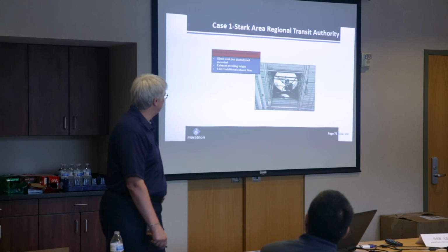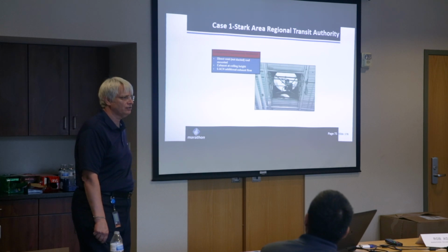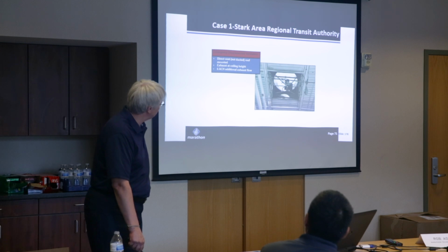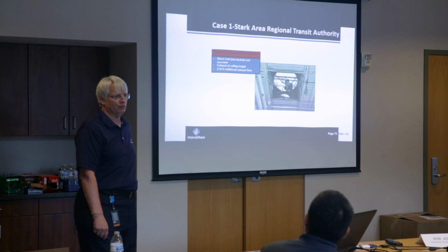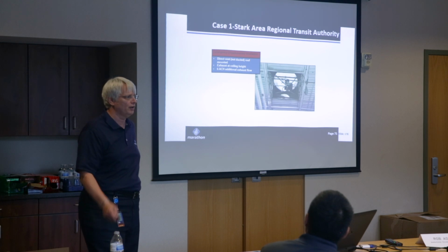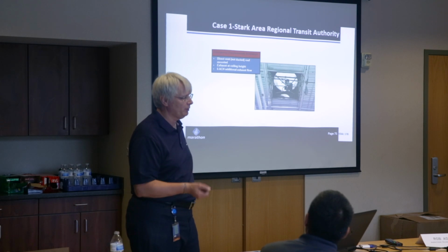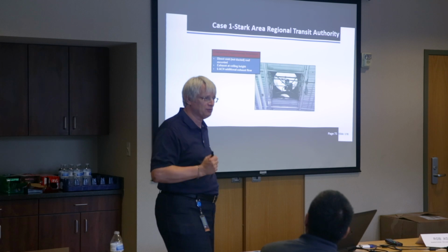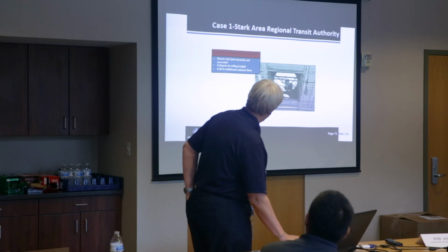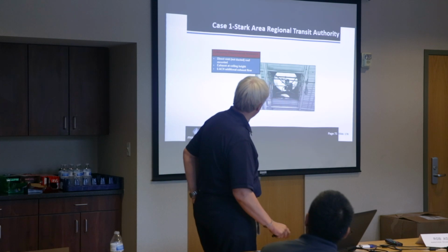They do have some direct vented supplemental exhaust fans, which I believe they actually run in the summer just for cooling as well, just to help move more air through the shop and keep it a little bit cooler. So if they're running out there today, don't panic. It doesn't necessarily mean they've got gas release. And those add the extra 6 air changes.